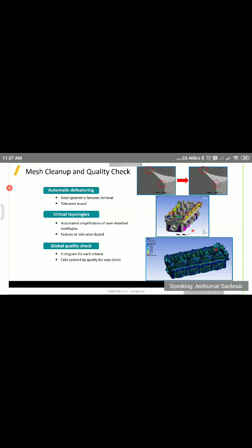We can try to do virtual mapping of a CAD over here, so that we can actually get the virtually bigger picture. The smaller edges will be converted to the bigger edges, smaller faces will be converted to the bigger faces. We can use the defeaturing tolerances to resolve such complex angles.